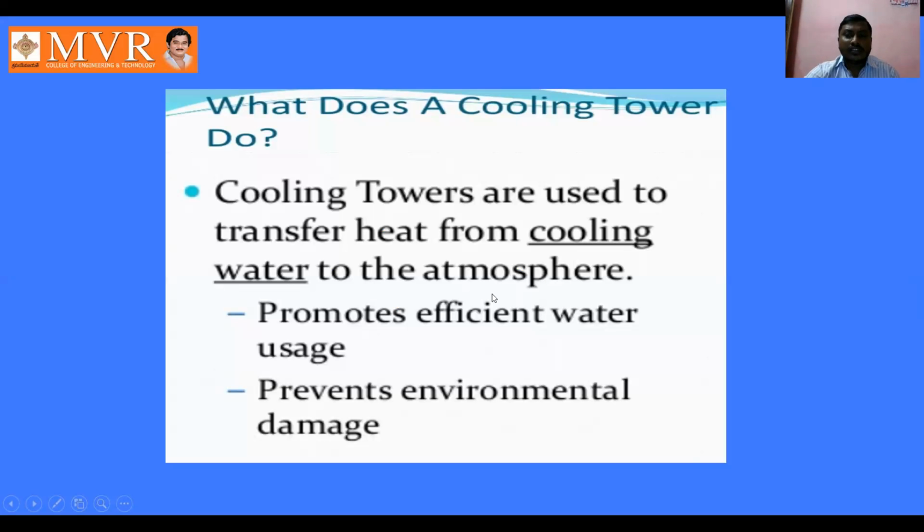In the natural draft cooling tower, as well as the forced draft and the induced draft cooling towers, the procedure is the same, but in the natural draft, the air enters the cooling tower directly without any external agent, such as fans.